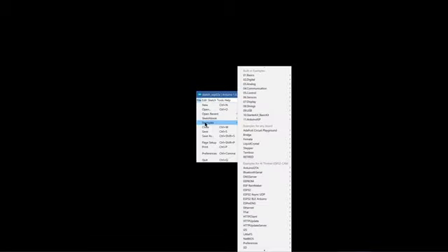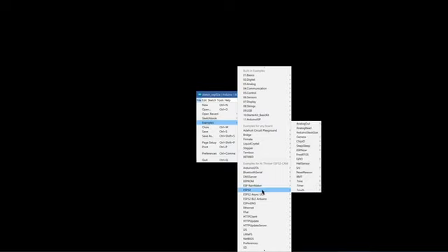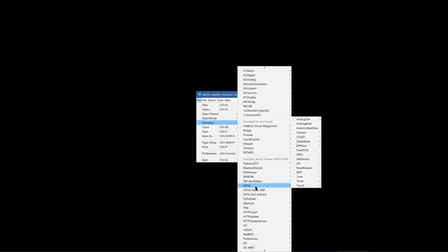After it's installed, close the Boards Manager, go to File, go to the Examples folder. You should now see ESP32 in the list. Go to Camera, open up the CameraWebServer.